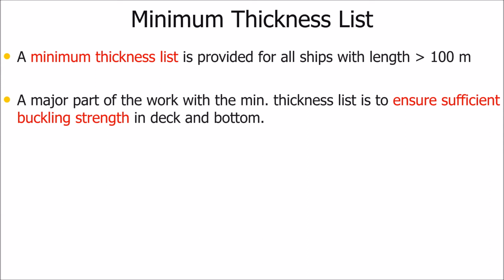The spaghetti is much stronger if it's straight than if you manage to bend it, right? It's the same thing here. So the thickness makes it bend easier. That's a problem for the high tension steel ships: the material is strong, but it's not that thick, and if it's thin, it would buckle easier.